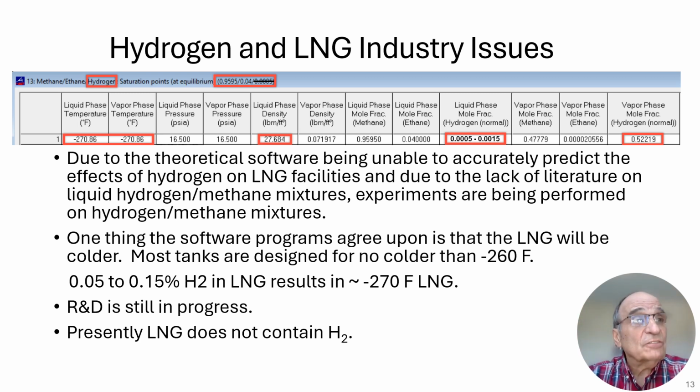Will the tanks self-stratify, auto-stratify? We don't know at this particular point. At least the literature does not show enough information, and R&D analysis is just not available to show whether the stratification will be an issue. R&D is still in progress. Presently, LNG does not contain hydrogen, but if hydrogen does get mixed into the feed gas, these questions will need to be answered.